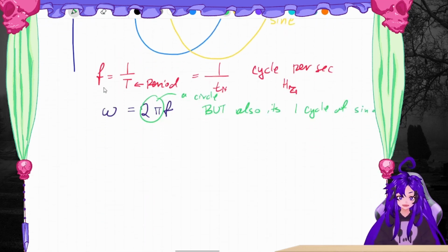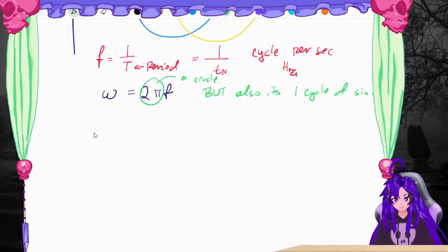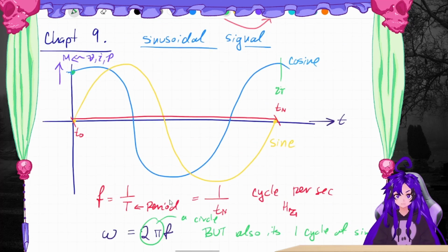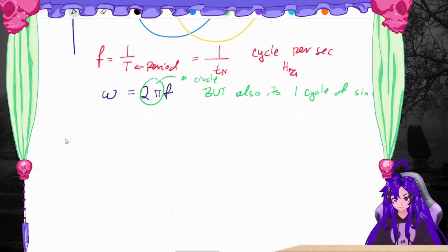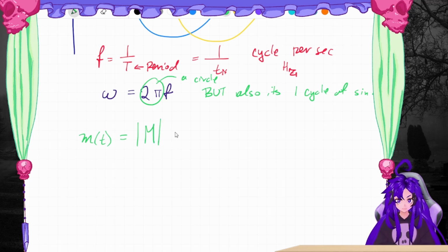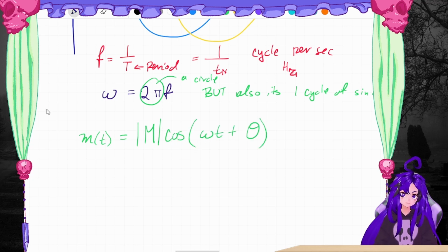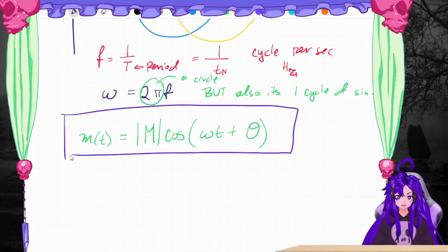It's what we do. So we have a standard, and so we can write this wiggle in a standard equation. Whatever our interesting value is, whatever's on y, as a function of time is the magnitude of it, or its peak, times cosine of omega t plus theta. And this is something worth writing down, because you're going to have to convert all of your answers into this.